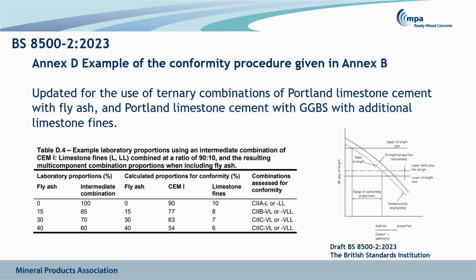Likewise, Annex D, which gives examples of how to apply that conformity procedure, has been updated for the use of the ternary combinations with Portland limestone cement with fly ash, Portland cement with GGBS, and then also to add additional limestone fines.